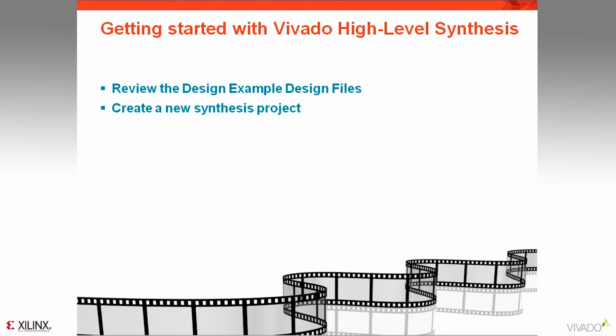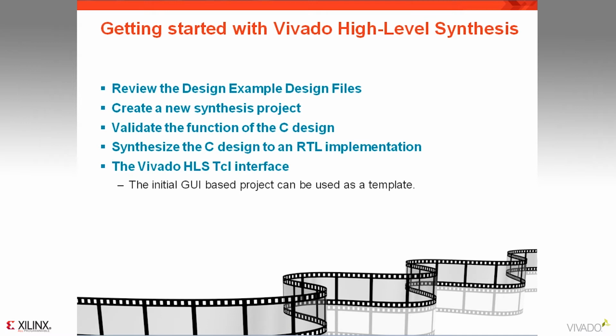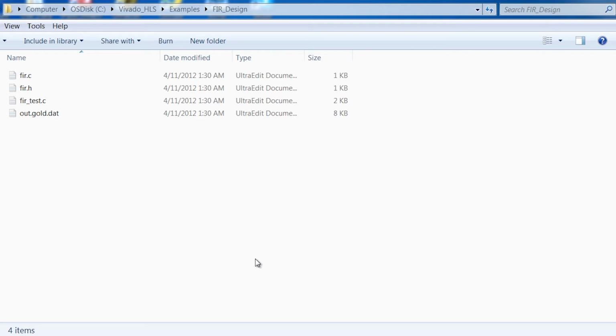We'll show how Vivado HLS can be used to easily create a new synthesis project, validate the function of the C design, and synthesize the C design to an RTL implementation. We'll then complete this video by demonstrating the Vivado HLS Tcl interface, showing how the initial GUI-based project can be used as a template. The design example used in this video is a simple FIR filter.